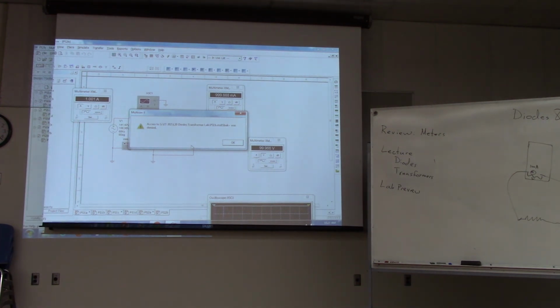Okay, so you're going to measure the resistance of the black leads, and then you're going to measure the resistance of the green leads. Now, these green leads, you'll notice that there's 3 of them. So this is a center tap transformer. The 2 solid green wires are the outer parts of the transformer, and the green wire with the yellow stripe on it is the center tap.